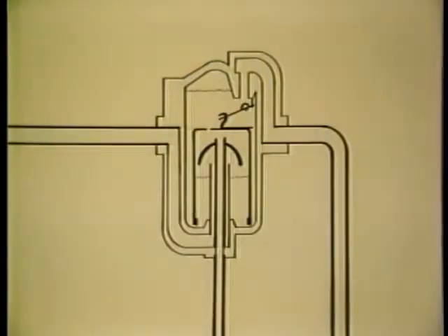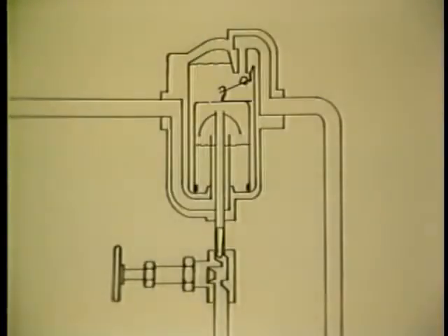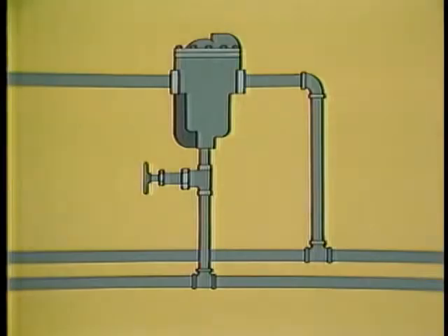The incoming condensate and gases are prevented from directly entering this secondary discharge by the shield. The condensate forms a seal, trapping the gases inside the bucket, as with the IB. Steam, flash steam, and any non-condensables rise around the shield to the top of the bucket. The manual metering valve is adjusted to remove these gases during full capacity operation or to meet the velocity requirements for purging the system. The DC may be piped in one of two configurations depending on the job requirements.